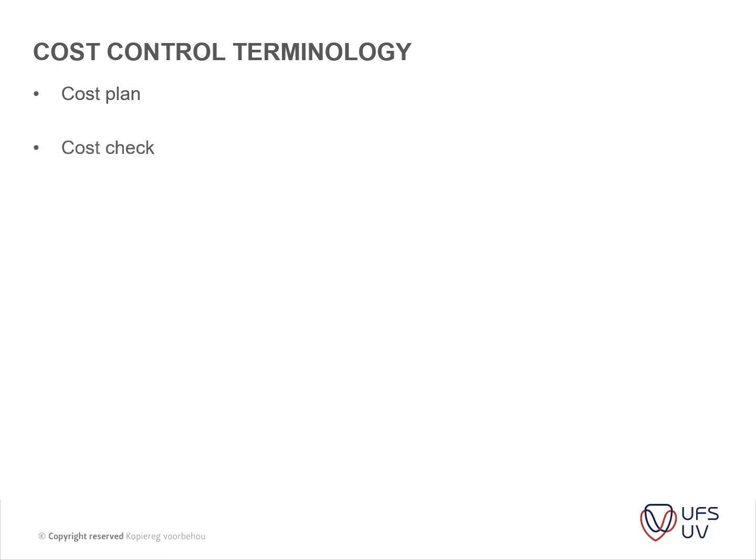And then your cost check. This is a process of checking the estimate against the allocated or available funds or the targets. So that's basically what the cost check entails. And then the approximate estimation is basically computing the probable cost of new building works at the same stage before the bills of quantities is produced, and it is essential to and an integral part of the cost planning process. So approximate cost is basically just the estimated cost of what the building will cost.